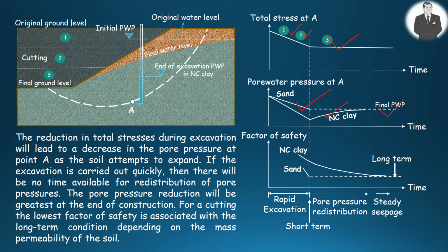For a cutting, the lowest factor of safety is associated with the long-term condition, depending on the permeability of the soil mass. If it is sand, the process will be quicker, but if it is intact clay, it may take several years.